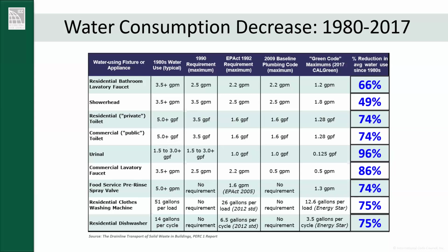Like a building like this, if they change all the shower heads and all the toilets, all the urinals to these modern rates, then the water is not flowing as much as it used to, so it stays in the pipes. So a lot of times, and we talked about the water quality, the disinfectants that the water plants add to the water dissipate while they're sitting in the pipes.